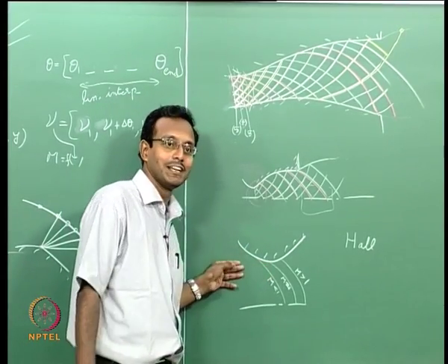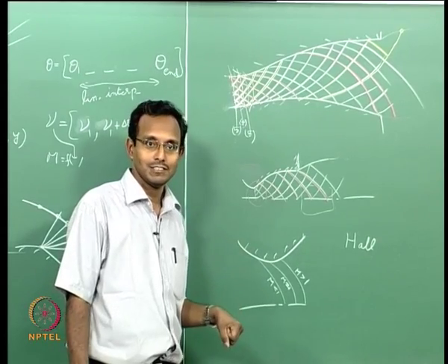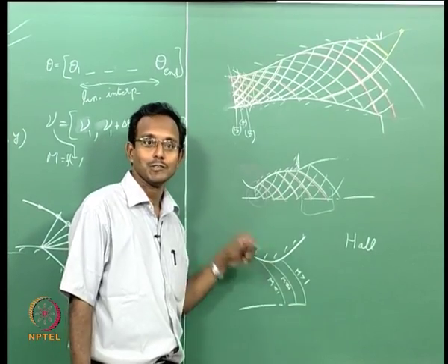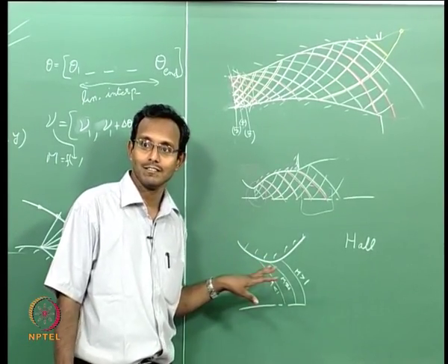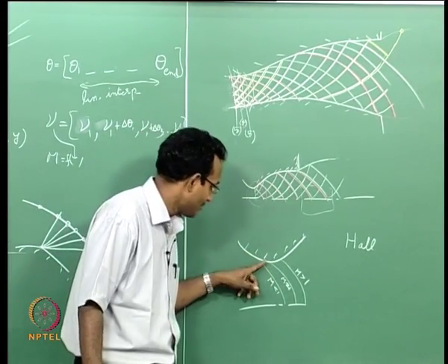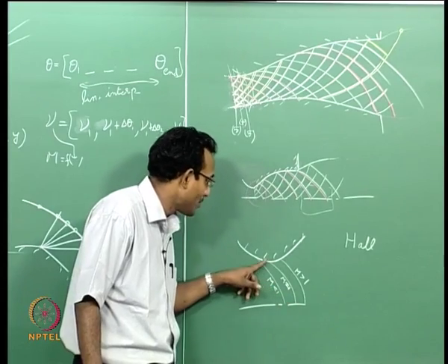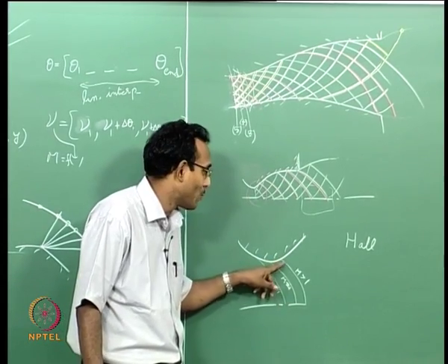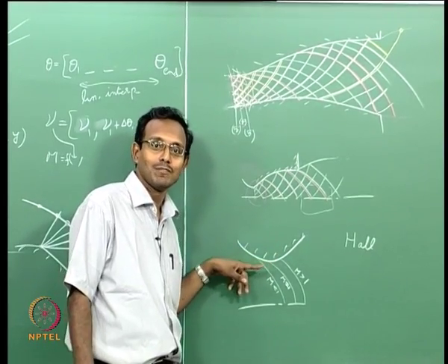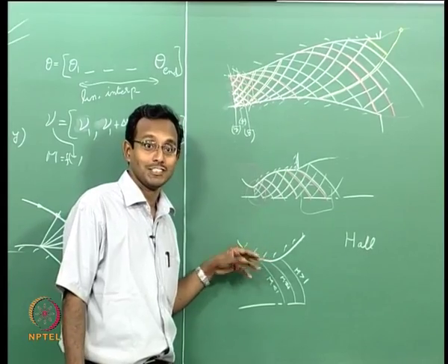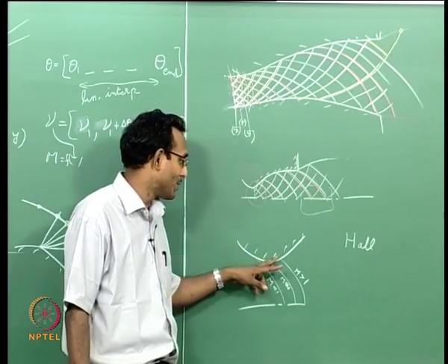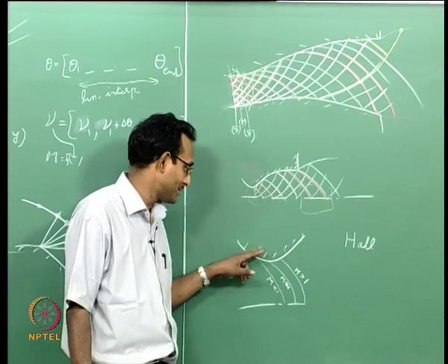We have used this data and created nozzles and they work well. We have used that kind of starting lines and then used MOC to create nozzles, and that nozzle works well. So I will say that data is reasonably close. We typically do not use the M equal to 1 line, we will typically pick 1.1 or 1.05, and the solution is not very valid for more than M equal to 1.2. It is transonic, the errors will become higher for M more than 1.1. So I typically use 1.05, 1.1 kind of numbers.